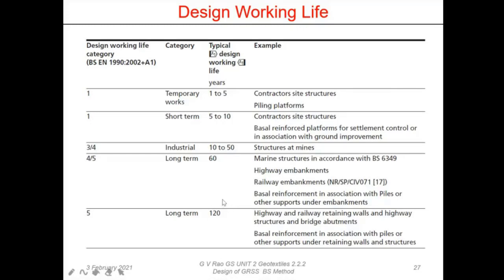In considering our long-term design strength, we have taken into account 120 years of creep, apart from other things. Okay, 120 years of any damage that is going to occur due to environment, due to wrong burial, due to exposure. So whatever factors we are going to consider will be this.